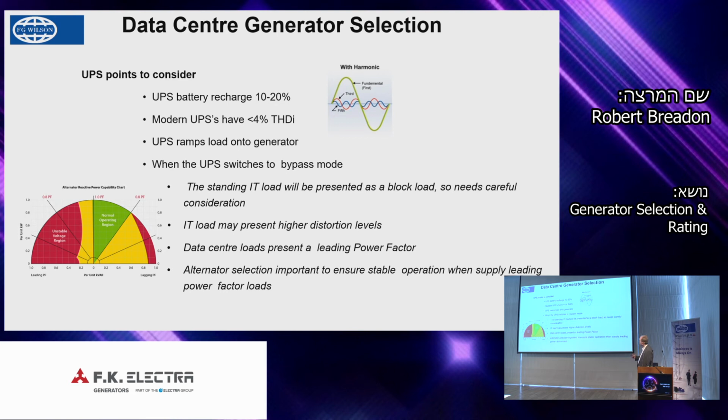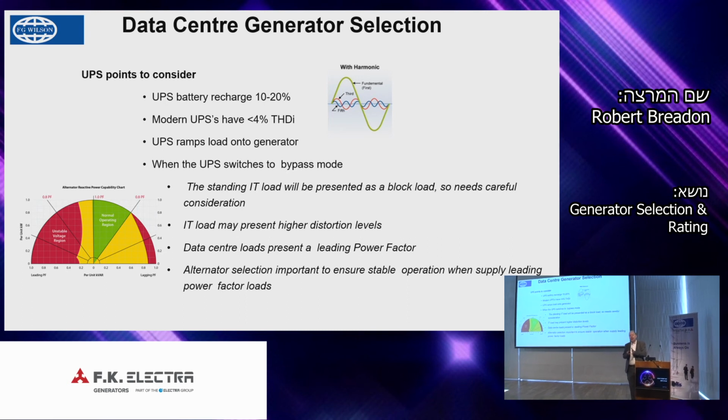if you're selecting a genset to back up a particular size of UPS, you have to consider not only the rating of the UPS, but also that when you're supplying the load, you want to recharge the batteries. So that forms an important element in your selection.